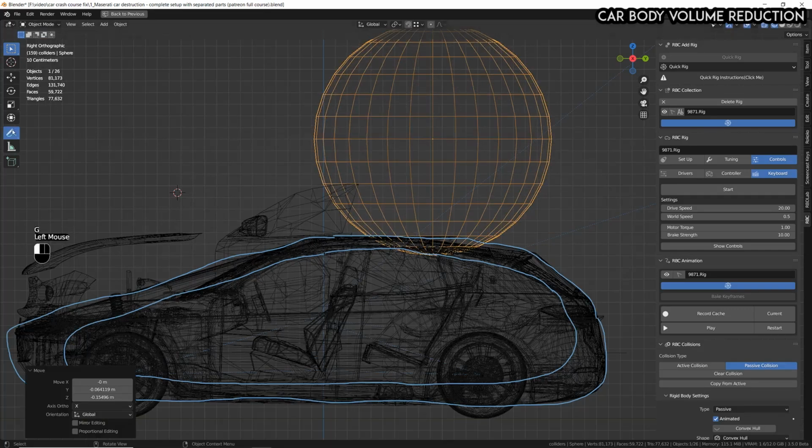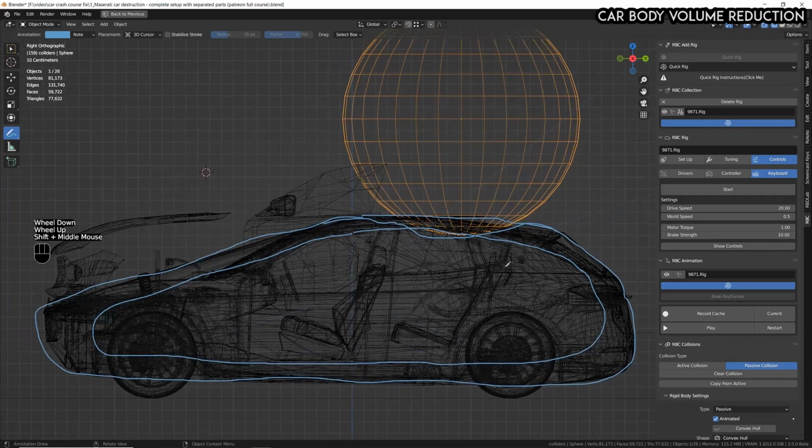And this is going to give me a more realistic deformation later, because the metal is going to go inside. And also, by doing this, we're going to have a proper contact between the car and, for example, the road whenever the car will start to roll over. So, in poor words, just do the steps that I will show you right now.